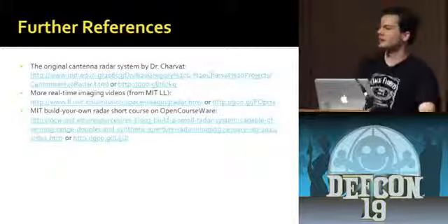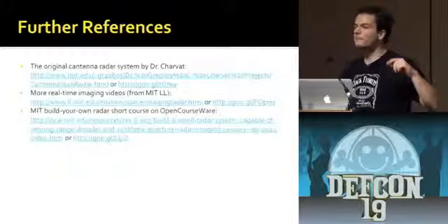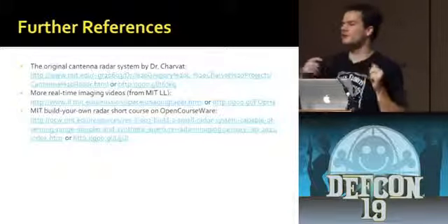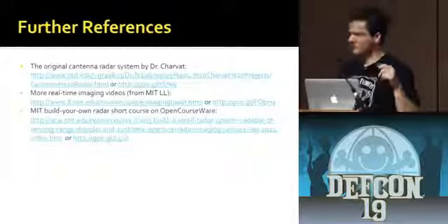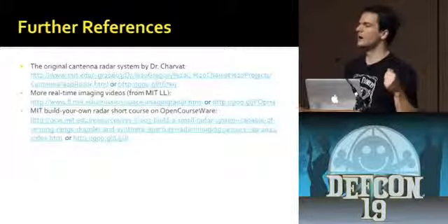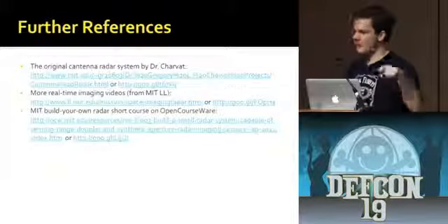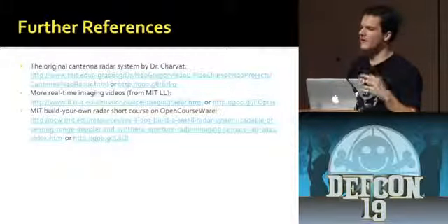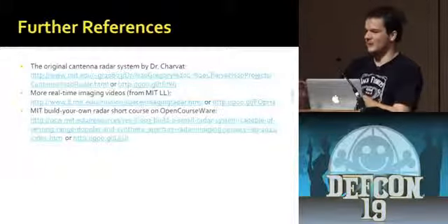Is the Doppler effect from a fast-moving object enough to mess up your position measurement? That kind of depends on what you're trying to do. If you're trying to measure something moving really fast, on the order of a plane, you might have some impact. When I was talking about it before, something moving 3 meters per second, like a person walking really quickly or a slow jog, produces a 24 hertz signal. At the chirp rates I was dealing with, 10 meters corresponded to like 667 hertz. So it wouldn't affect it too much, but that all depends on your chirp rate and your bandwidth and a bunch of other factors. You could make it have an impact or not.